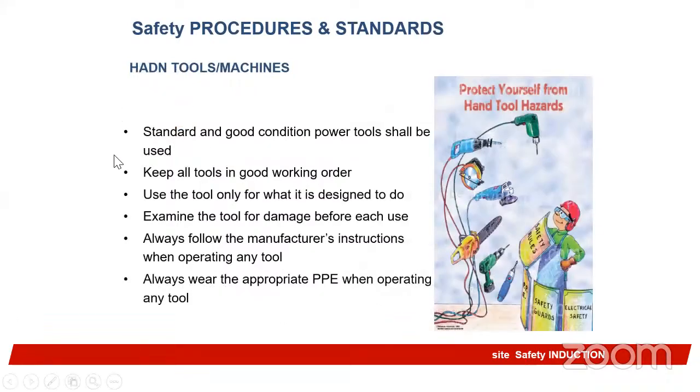So you also talk about hand tools. You talk about various hand tools too. Talk about the standard and good condition power tools that you need to use. Keep all tools in good working order. You talk about the safety use of all these tools, use of PPE while using them, regular inspection of all these tools, and always following manufacturer instructions when using these tools. These are the things you communicate to the workers, and why it is important for them to understand the safety aspect of these tools.